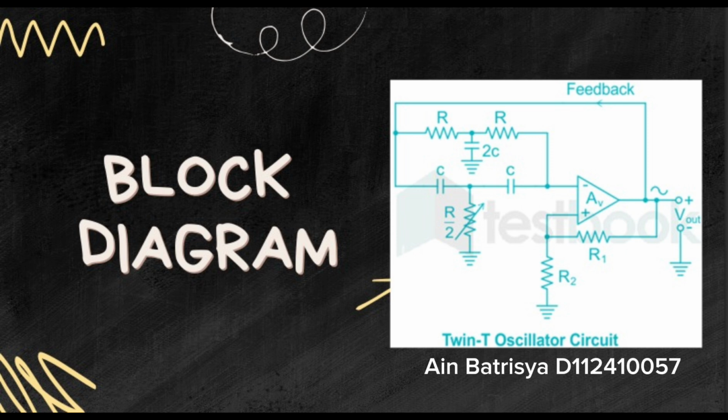Okay, at the left side of the circuit, we can see the twin-T network. It consists of two T-shaped RC branches. The upper T network is made of two resistors, R, and one capacitor, 2C, in the middle. The lower T network is made of two capacitors, C, and one resistor, R/2, in the center. These two networks are connected in parallel, forming a band stop filter which blocks a specific frequency from passing through. But when using feedback, it allows the frequency to oscillate by feeding it back with the correct phase shift.